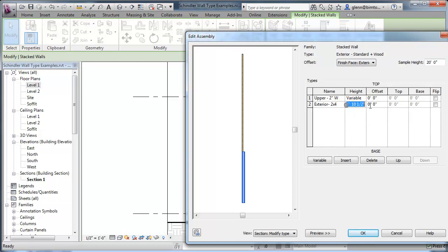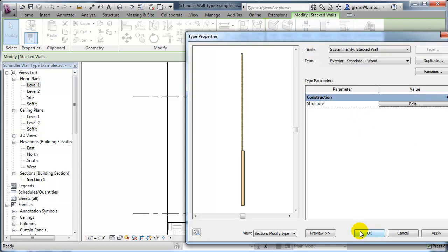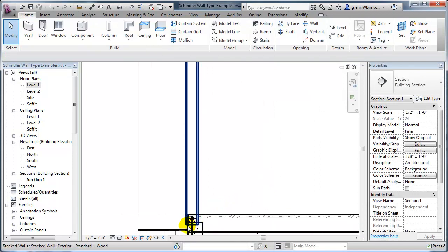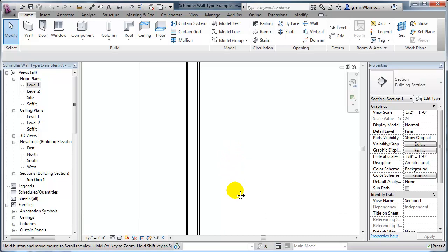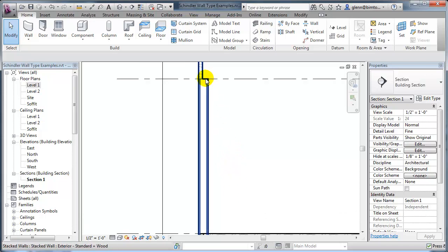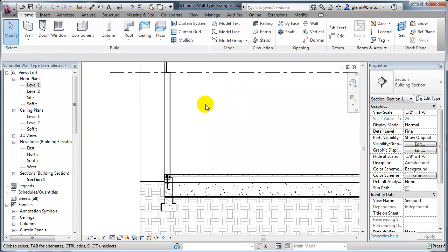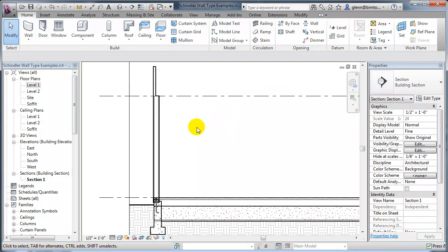I'm sorry, that's a little bit confusing. I'm trying to accomplish sort of two things with a single wall, and I think this will actually work out better for us in the long run. Again, we'll only do it to the exterior walls because the exterior walls need to wrap down, but the interior walls don't. Okay, now I can have the exterior walls come down 4 inches and still have that 6'10½" actually end up at the soffit level. Okay, that's looking pretty good over there.